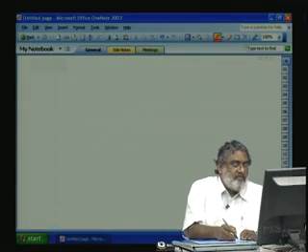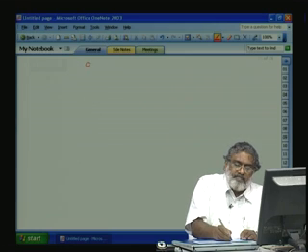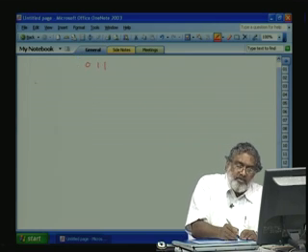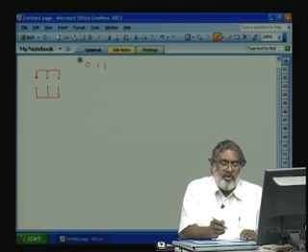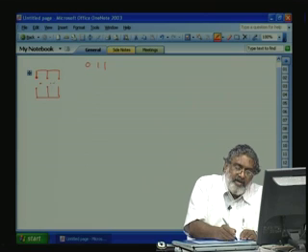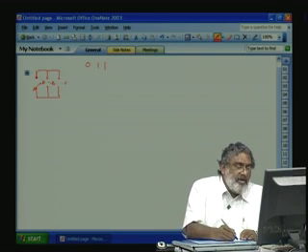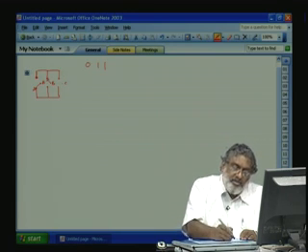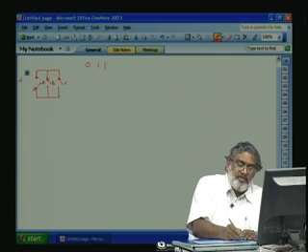Now let us take the fourth state. Fourth state we will take as 0, 1, 1. From the pole state 0, 1, 1, it clearly indicates where we have to connect the inverter poles, that is ABC poles. A will be connected to 0, that is the bottom side. B will be connected to the positive, so the top switch is on in the B leg. This is 0, 1, 1. This is our fourth state.